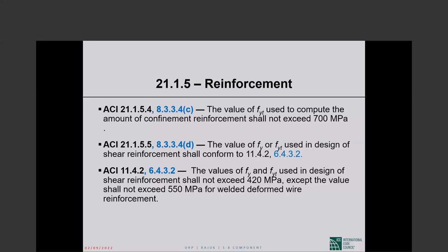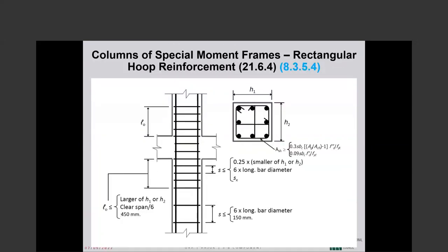But when the same reinforcement acts as shear reinforcement, we should not count on yield strength beyond 60 ksi, because if we do, we will be looking at wide shear cracking in our beams, and that is very objectionable. So in the shear carrying role of the transverse reinforcement, your limit is 60 ksi, 420 MPa.